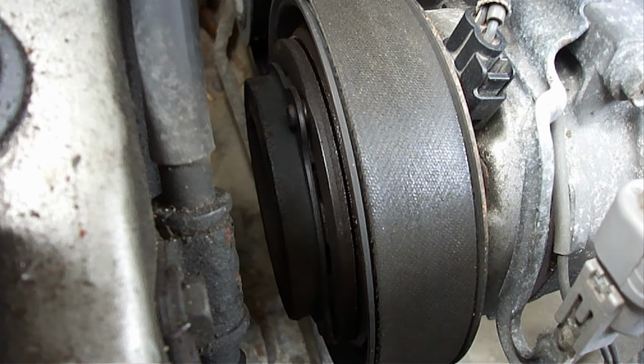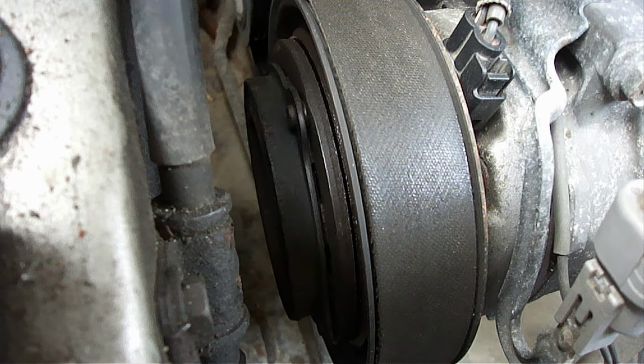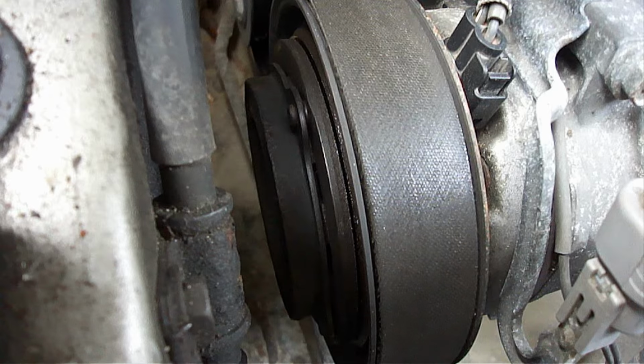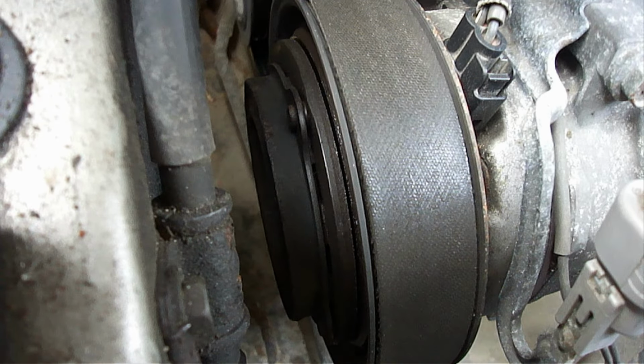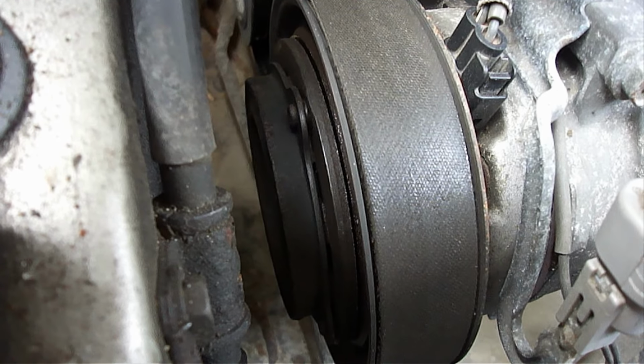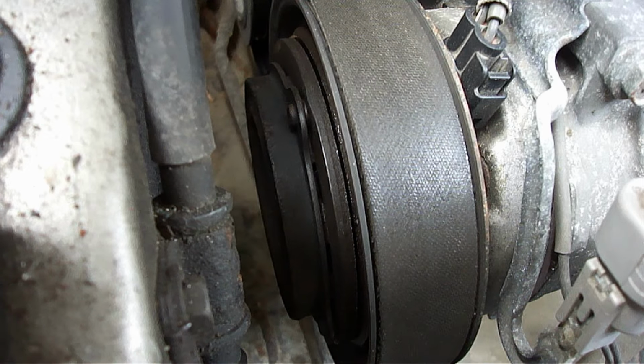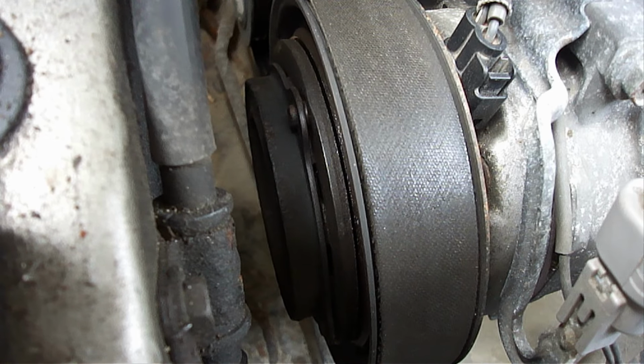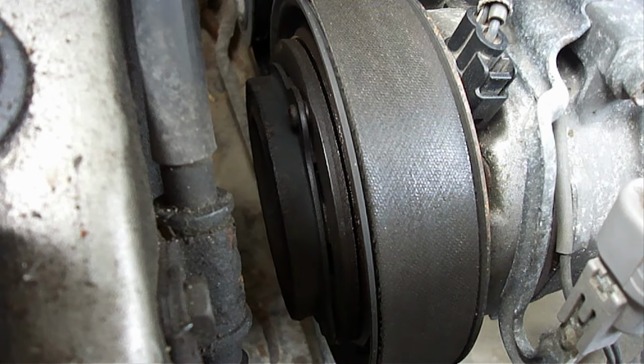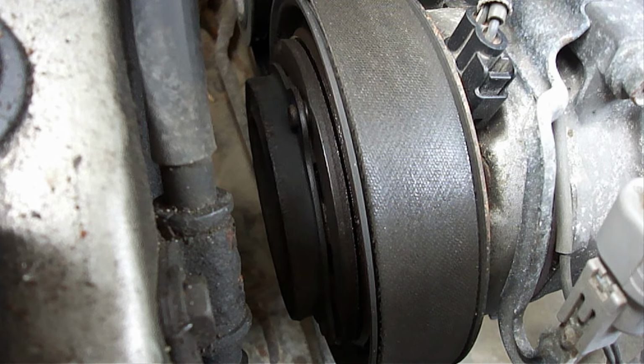Another common symptom of a bad pressure switch on either the low pressure side or the high pressure side is the compressor clutch will turn on and off rapidly when the air conditioner is on and the vehicle is idling, making it unable to properly cool the vehicle. A bad high pressure side switch will usually cause overheating of the compressor.